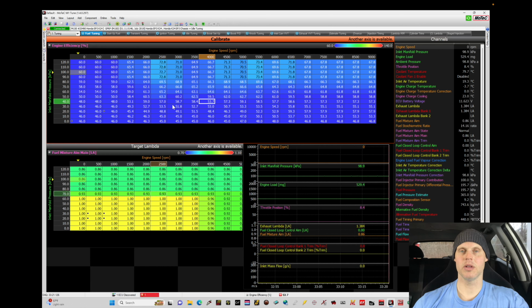Now this is going to be a little bit of a problem with Motec in the sense that we don't have two volumetric efficiency tables and two spark timing tables and two variable cam target tables within the programming here. We have to make everything work within one table, which is definitely a disadvantage compared to other systems like Mtron or Link or Haltech that give you a lot of flexibility to have different table switching.